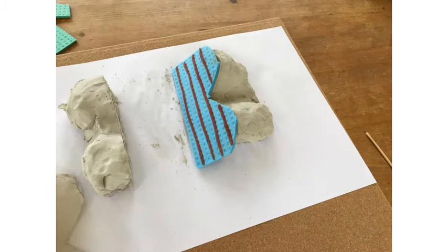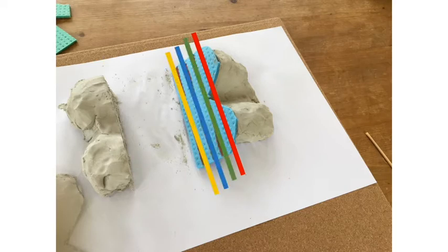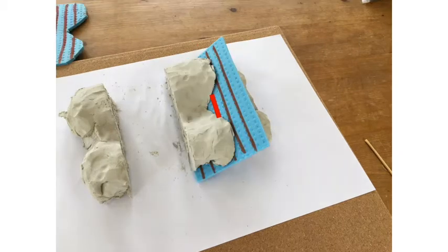Well, let's look down on this sponge again. Here we are, so we're looking down on our blue sponge with some structure contours drawn on, and the one we've been looking at, we joined up these 2 points of equal elevation on the landscape, where the boundary of the top of the blue sponge comes up to the landscape, and we join these up to make a continuous structure contour on the top of our blue sponge layer. And there's an array of other contours that we could draw, equally spaced, running down the dip of the blue sponge. And of course, this blue sponge layer existed with a greater extent. It extended into what is now above ground.